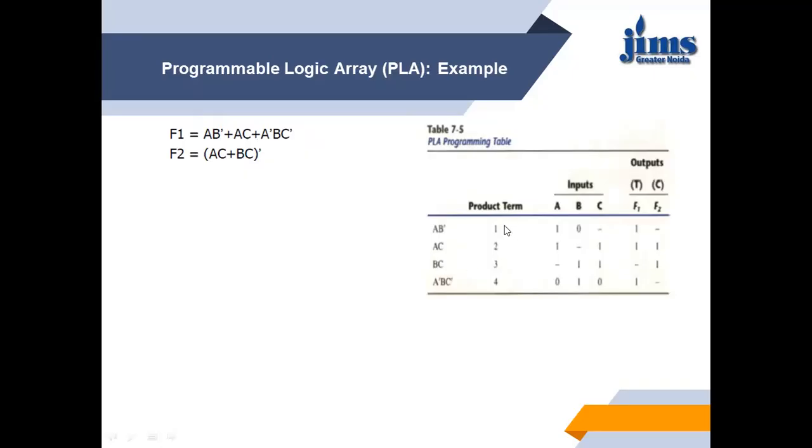So in F1 and F2 we have total 5 minterms, but taking AC as common, we have only 4 product terms. So we need not use a 3:8 decoder, but only 4 AND gates. This is the major difference between PLA and PROM, because when we are using a decoder, it will give an output of 8 product terms. So here we do not need 8 product terms.